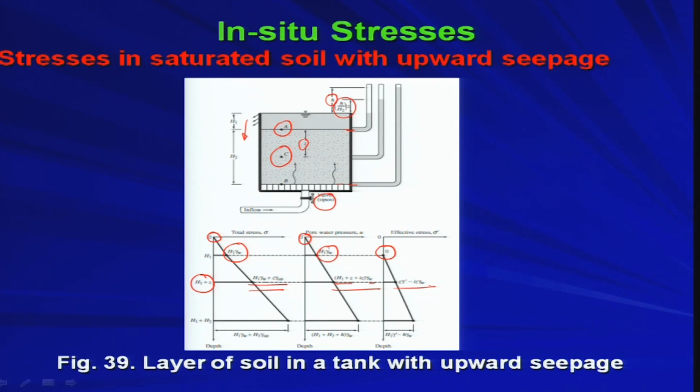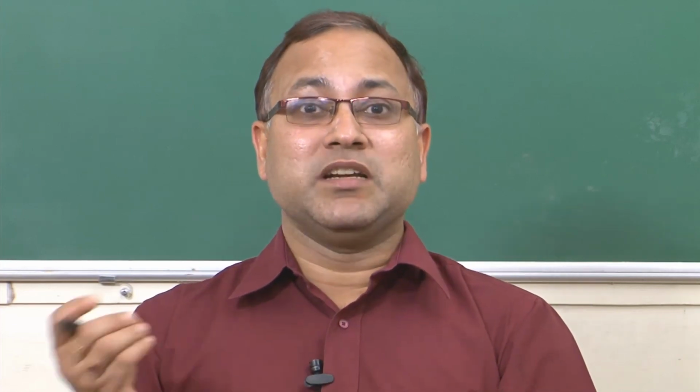If there is no seepage, whatever effective stress you are getting, now because of some seepage your effective stress is going down or decreasing, right. So, you have to be really careful when you are designing some geotechnical structure. If it is under static water, where there is no flow happening in the soil body, then you get a certain effective stress. You may get increased or decreased effective stress due to the direction of the flow, of course, that is true.